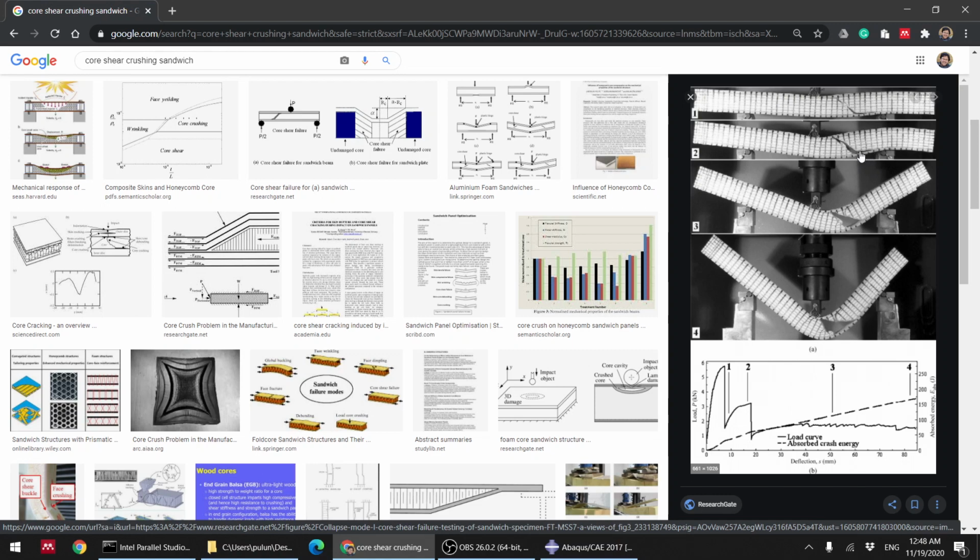Here there's a crack. We call it delamination, between the core and the skin, and then the core itself has a crack, and this crack is inside the core. So we want to model it not using cohesive elements, sorry, because we don't know the exact location. The cohesive element in Abaqus is basically the predefined cohesive element, right? I forgot what the name of the predefined one is. Is it intrinsic cohesive element or extrinsic cohesive element?